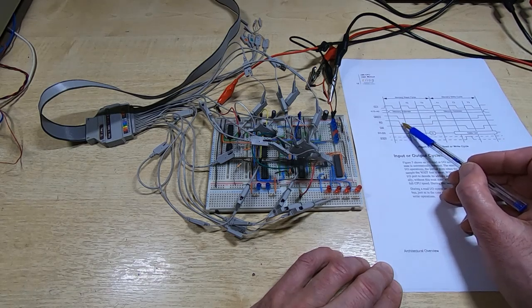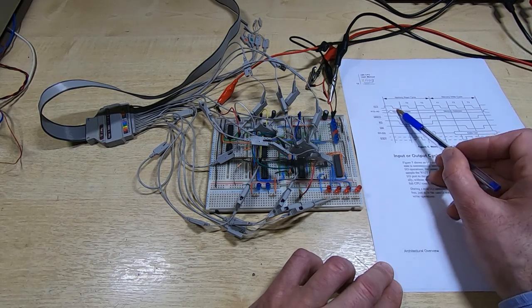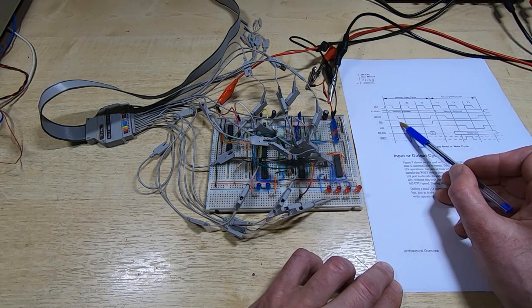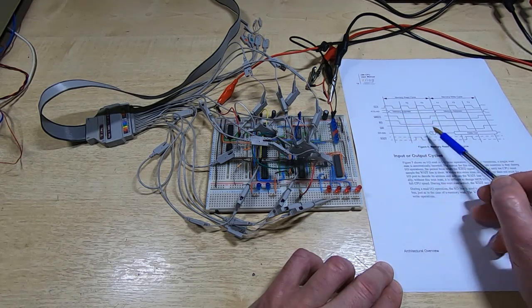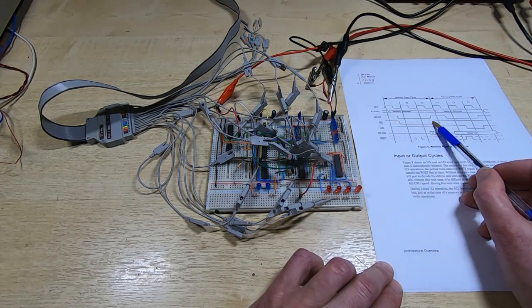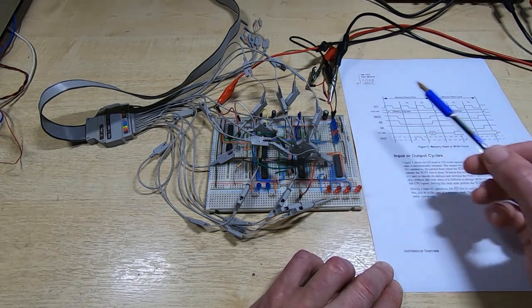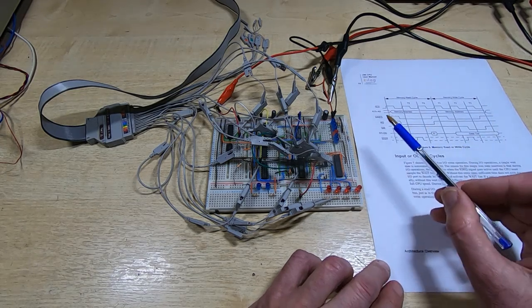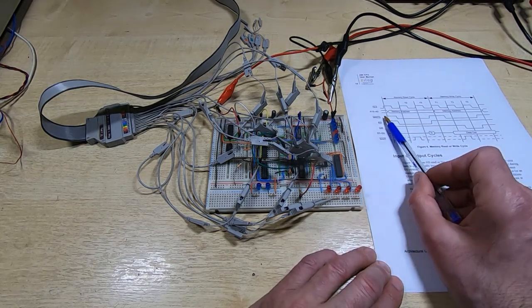And what we can do is use an external data selector so that the signals here select the various channels on the data selector, and assuming that the inputs to the data selector are set to high or low values, we can just feed those through to the output, and then the output will take on whatever form we want it to. And it will make more sense when you see the circuit, but I won't show it in this video, but I will come back in a future video and show that.